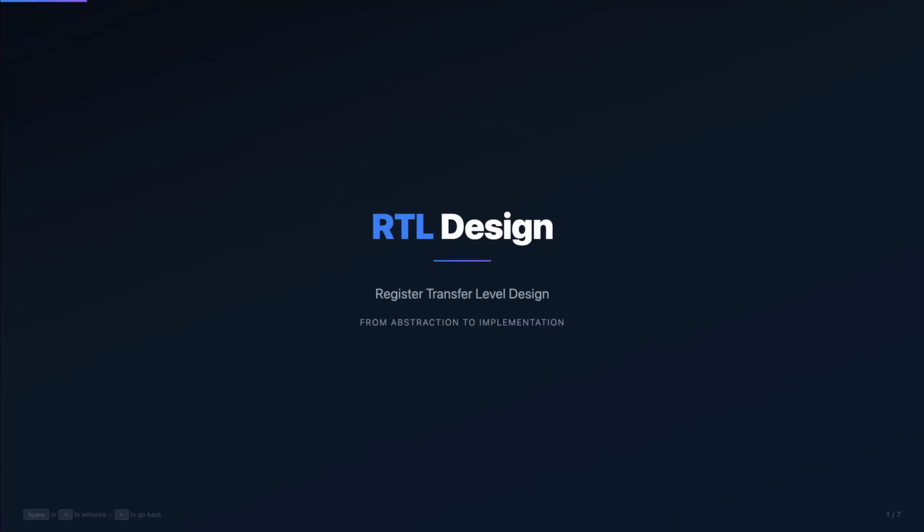We've reached the point in the course where we need to talk about RTL design. RTL stands for Register Transfer Level, and it's a level of abstraction that helps us more effectively design certain digital circuits. So let's talk about this in a little more detail.